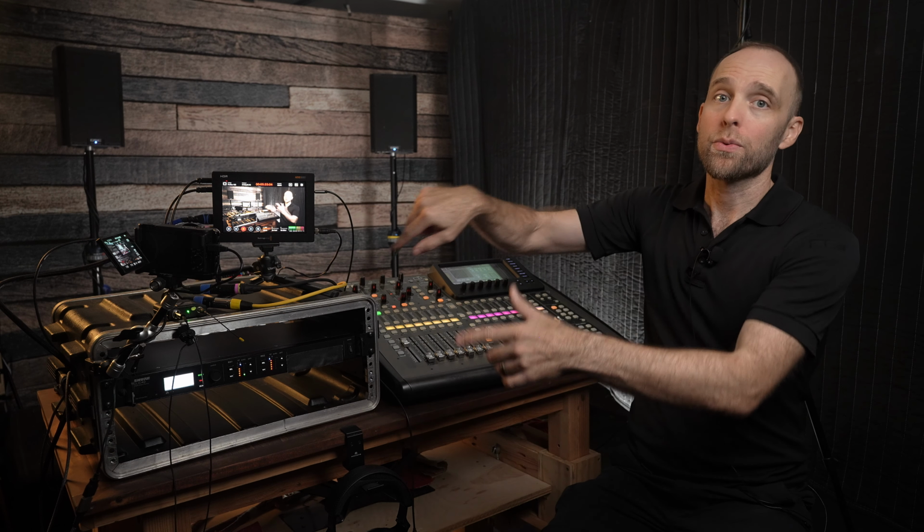So you should be able to hear the result of this bad gain structure that I've set up because there's a lot of noise in the audio in this video. There's this decently loud hiss. And this is the result of poor gain structure. And this is the raw audio completely unprocessed as it passes through this system. And the reason this audio has so much noise is that I've gain structured this system improperly or backwards. And this is unfortunately how I see a lot of live PA systems set up, but that ultimately cause the audio personnel more problems that they can't get themselves out of.